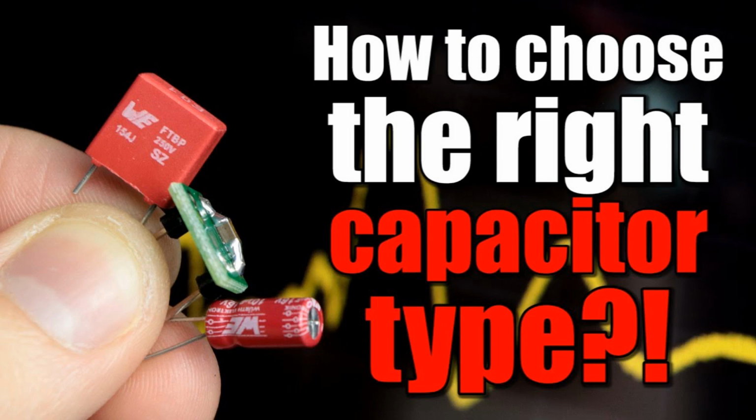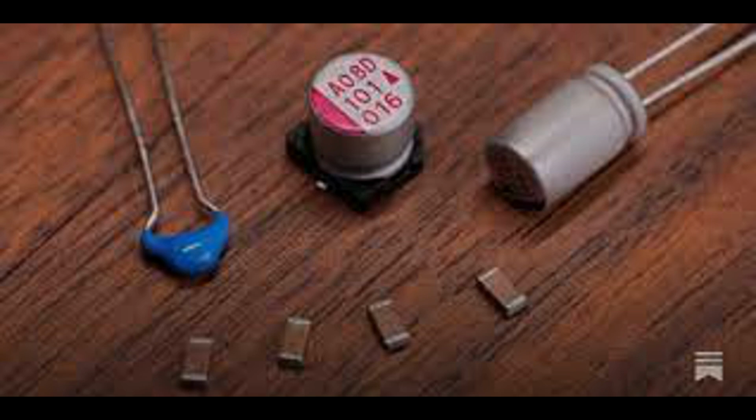Radio tuning. Description: capacitors are used in radio receivers to select specific radio frequencies from a broad spectrum of signals. By adjusting the capacitance, the receiver can tune into different radio stations. Example: in an AM or FM radio receiver, variable capacitors, or tuning capacitors, adjust the resonant frequency of the circuit to match the frequency of the desired radio station.